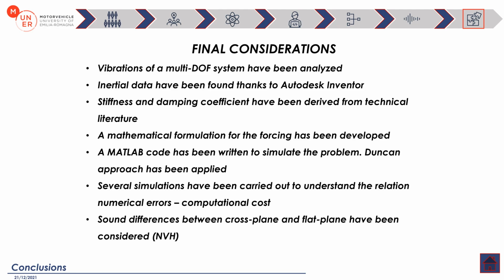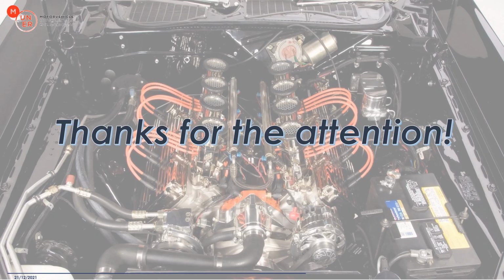In the end, the project has led us through the analysis of a multi-degree of freedom system and through the formulation of the theoretical model, beyond the numerical simulation of an engine. The importance of computational cost and time has been considered. Moreover, a focus on the sound of the engine has been done to better understand the differences between flat and cross-plane V8 engines. I have concluded. Thanks for your attention.